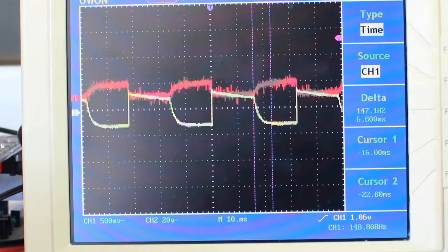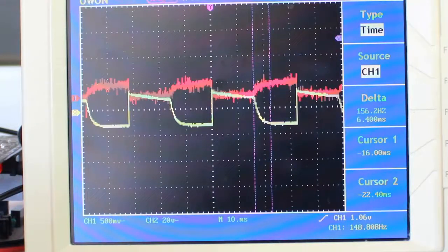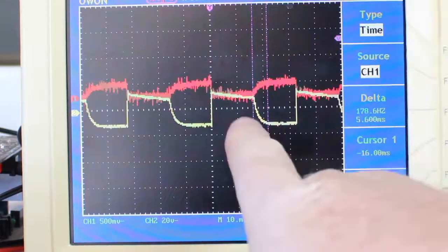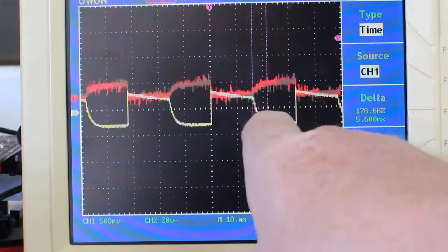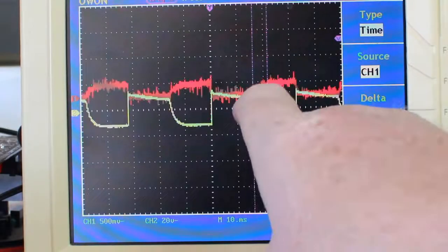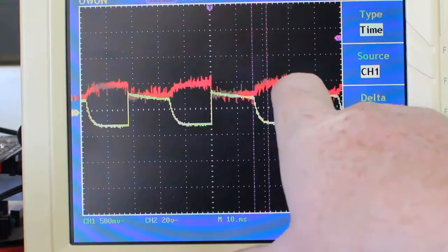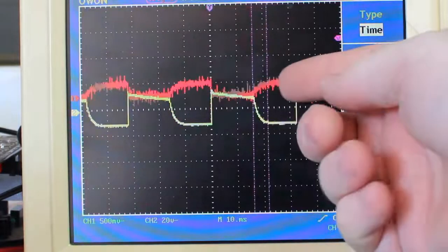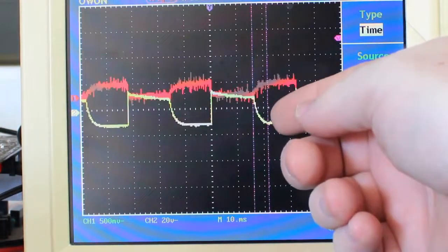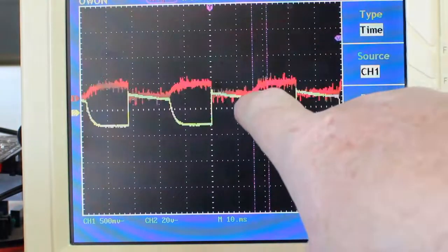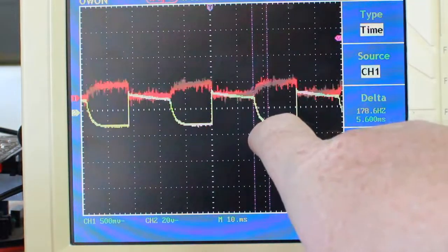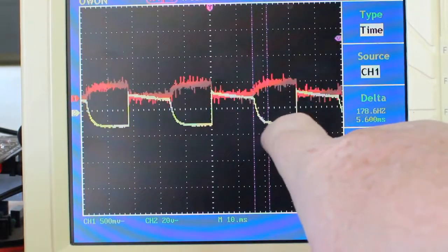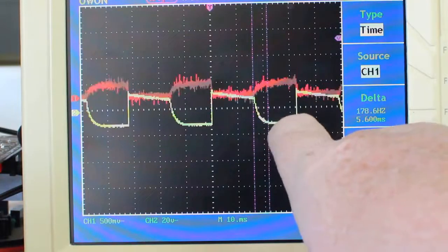Now what we're going to do is find our point on the voltage line itself, where the voltage has changed all the way down here. If we call this cursor here 97.3%, which is 5 time constants of the magnetic field, remembering in a coil there's 5 time constants to get the magnetic field up, we find that the change in voltage from that cursor to this cursor is the same as the change in current up to here to get to 5 time constants. After the voltage has gotten to the 5 time constants, it flattens off. There is no more voltage to be generated. We can't generate any more voltage.